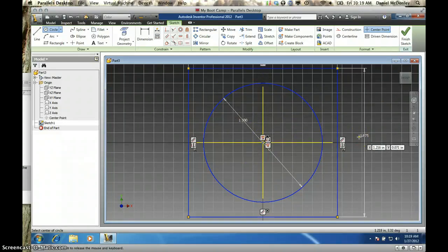So now from here, I'm going to also create another circle. These cubes are going to be a little bit easier to deal with. So I'm actually creating the size of my cube here by making these circles. So I'm trying to choose big round numbers. The 1.875 is just a reduced from 2. The first circle at 1.5, and this one let's make it 0.667. There we go. And you can see again it is constrained.